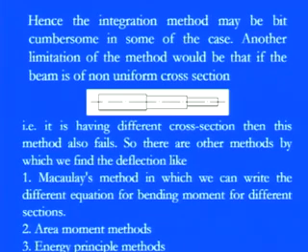The second method is the area moment method. In this chapter, our focus will be on the area moment method. We have a bending moment, and under the bending moment diagram we have a certain shape. Because of the loading conditions and the cross section of the beam, they will definitely give a specific bending moment diagram. So our focus will be on what the area under that diagram is, and based on that we can simply find out that this much deflection or this much slope is there.